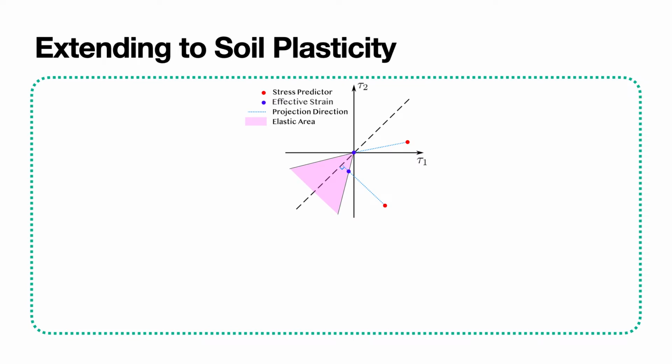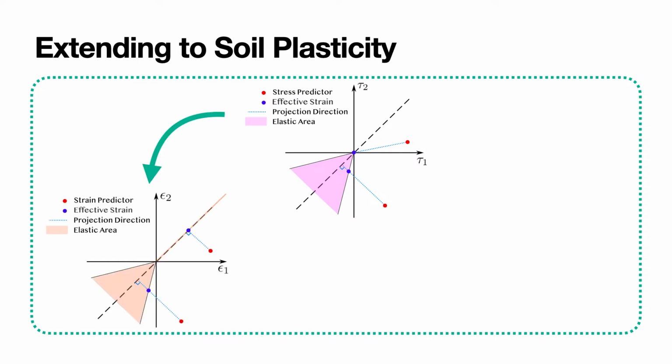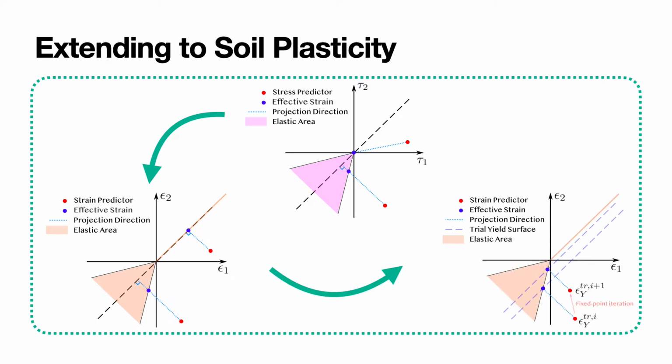For other plasticity models such as Drucker-Prager, we extrapolate the yield surface in the principal strain space to achieve volume-preserving projection for the definition of the augmented part of our elastoplastic energy, and use iterative yield stresses for the integrability of forces. The force equilibrium and yield stresses are solved alternately. At each iteration, each particle experiences a locally constant yield stress.